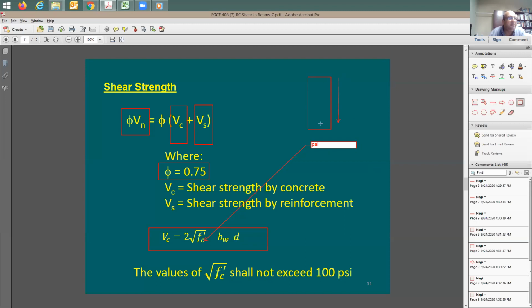So we need the rebars. If it's like some box, this is going to be the middle of it, right? To the top of the concrete, this is going to be D. So this area here is going to be the area exposed to shear. This is going to be the sheared area of the beam. And we ignore the bottom cover, because it's going to be cracked anyways. So it's going to be the area of the concrete times the allowable stress.